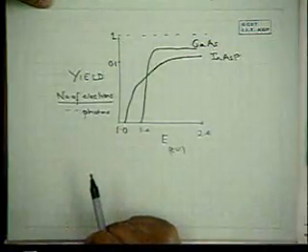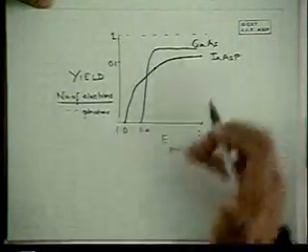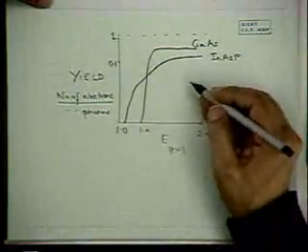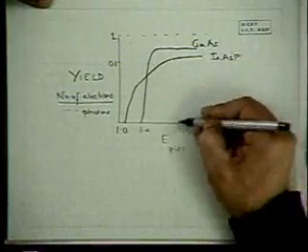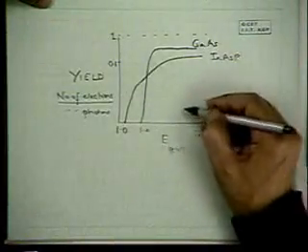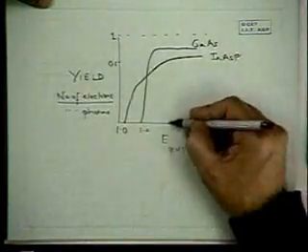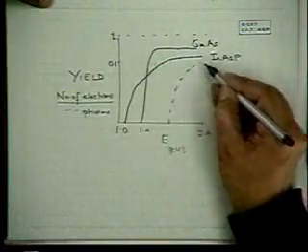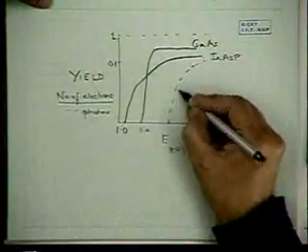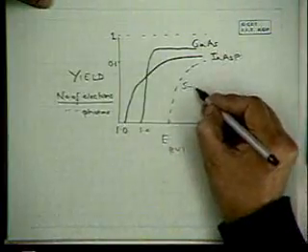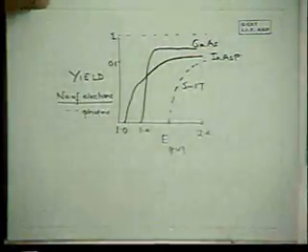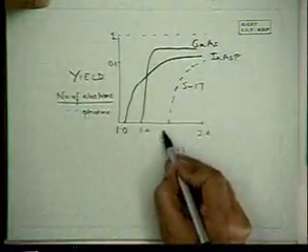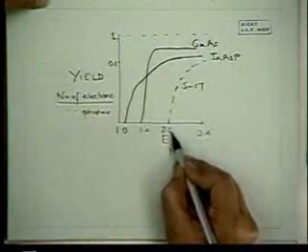If you compare this with conventional photoemitters, their response will only start at about somewhere here. Conventional multi-alkali, S17, etc. The response would only start at somewhere near 2 eV.